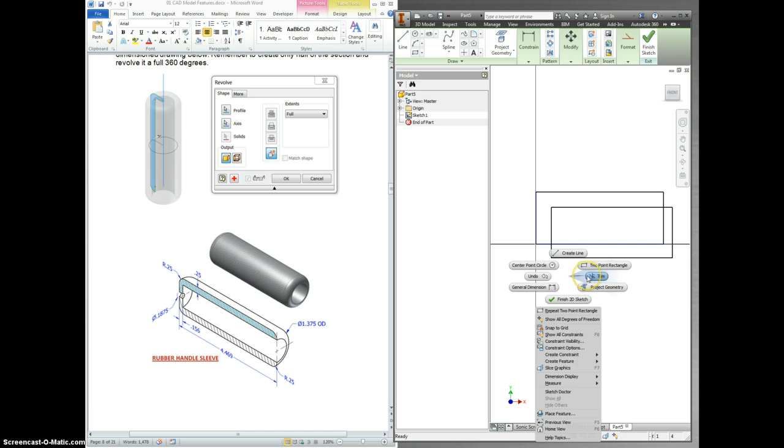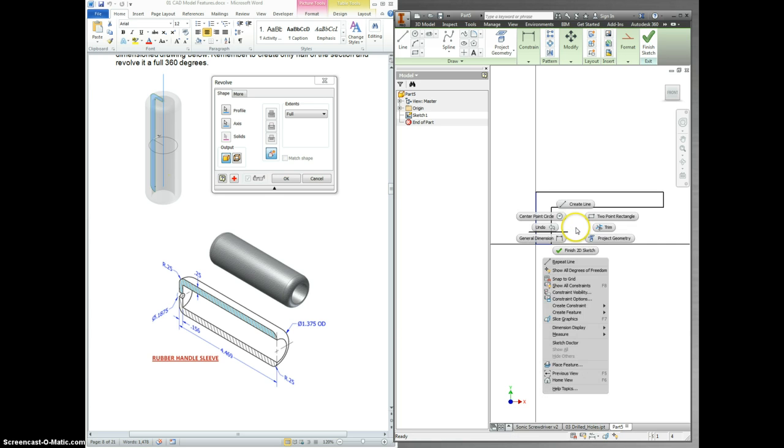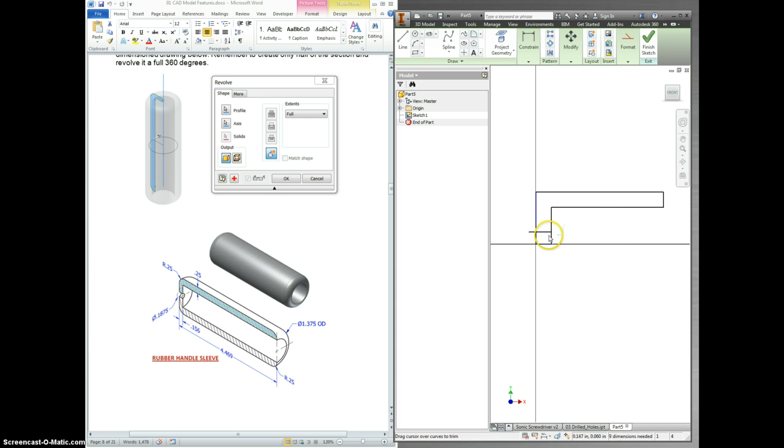Right click and pick trim. Alright, I don't want all this stuff in here. There's my basic L shape. Okay, let's switch back over to line. I'm going to make a horizontal line through here, select trim, and I actually hit escape and then trim, which you didn't see. But you're going to trim that stuff out.